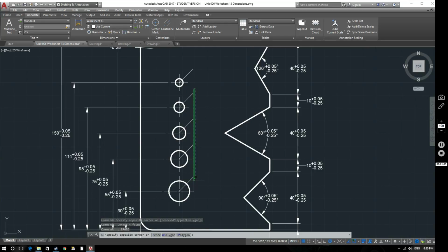So we'll just select those and make sure we're not infringing on anything else. So let's extend this one by another, say 5mm should be acceptable, and let's copy and paste that. So let's copy that and we'll make that the base point again.